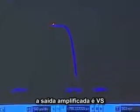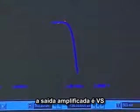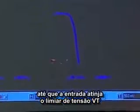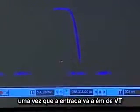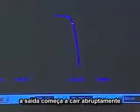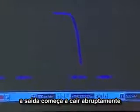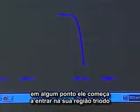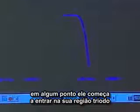So notice that here, that's the same curve, the transfer function, and for the MOSFET amplifier, the output is at Vs until the input reaches a threshold voltage Vt. And once the input goes beyond Vt, the output begins to drop precipitously. And at some point here, this begins to go into its triode region.